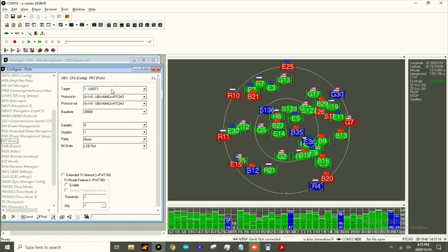For UART1 and UART2, this does not really impact the functionality, but for the sake of completeness, I tend to prefer a higher baud rate of 115200, just to ensure consistency across the board. So we'll change that to 115200 and send that through.